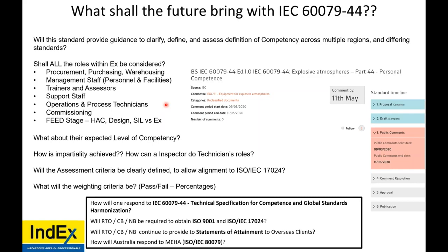Now, during front-end engineering and design, taking into account hazardous area classification needs to happen. Then the design happens after classification. But we've experienced many times in the industry where a wholehearted design or specification is copied and pasted from one project to the next, and then it's made to where the hazardous area shall conform to the design. This can lead to issues. That is not the correct process.